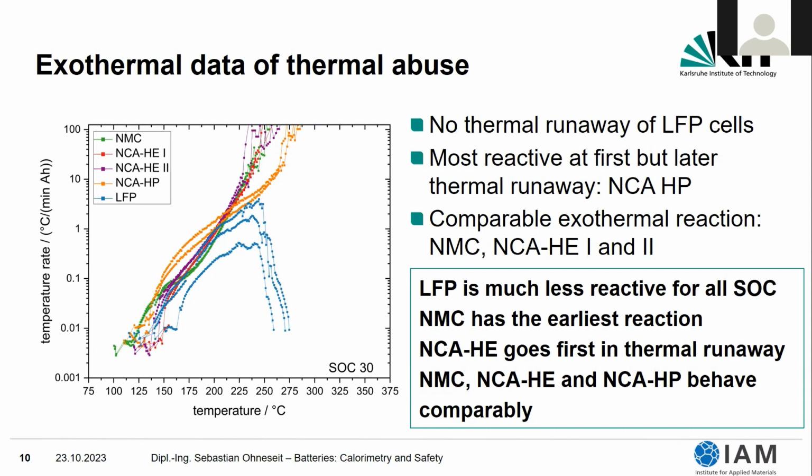And we actually went until 350 degrees. But everything that was still happening here was just a little bit up and down and measurement noise. So there was no decomposition reaction from the LFP cells. They stopped thermal decomposing by themselves, even though we continued to heat. So that's why we considered that they do not have a thermal runaway at SOC30.